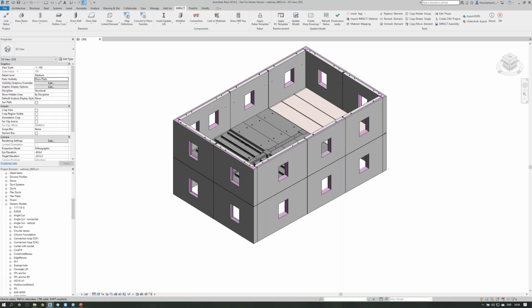When we look at it from a Revit perspective, the loadable families are, as you probably know, created by the user. You create in a separate file the geometry and put parameters and other information on it, and then you use them in the actual model. While the system families are basically just families that are created through the program. So you don't need to prepare those families in another file, but you prepare them in your project template basically.